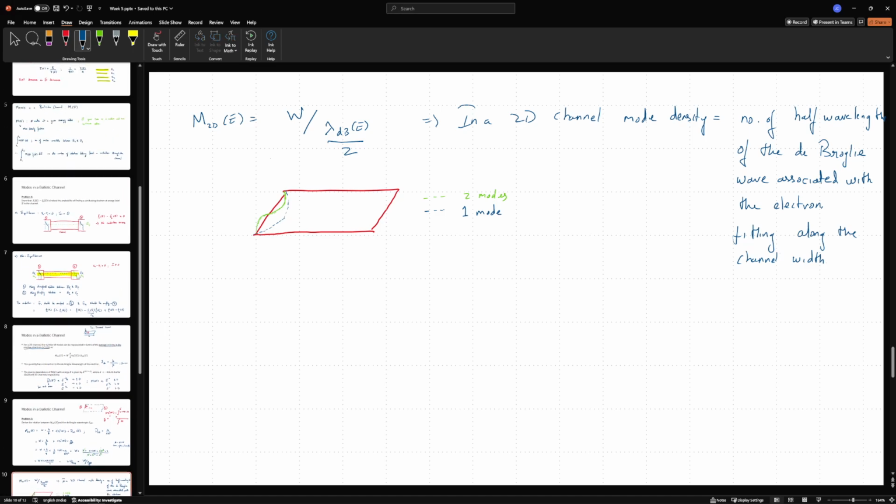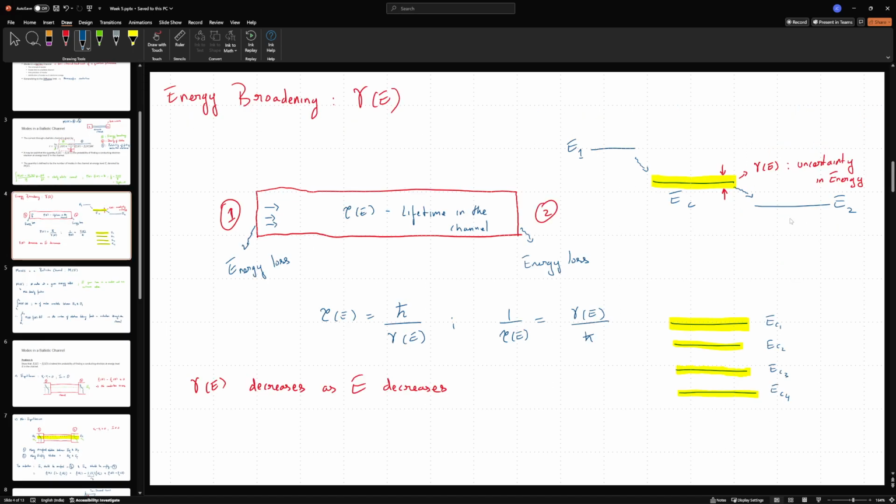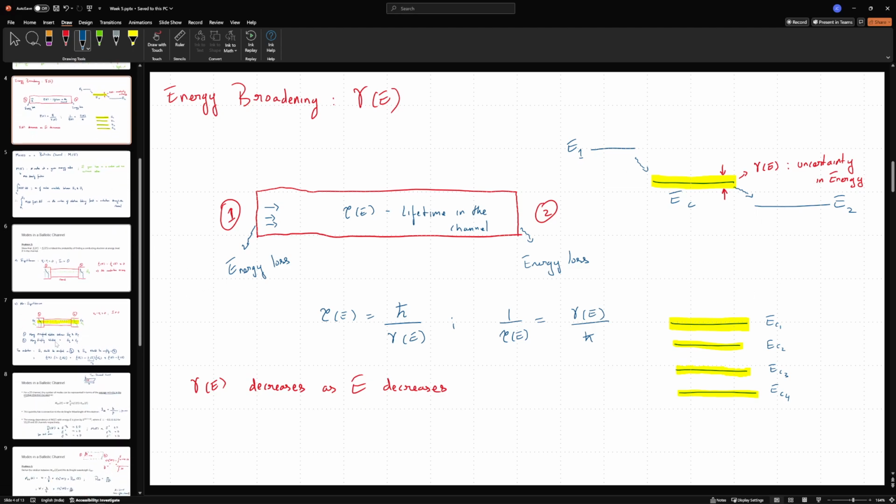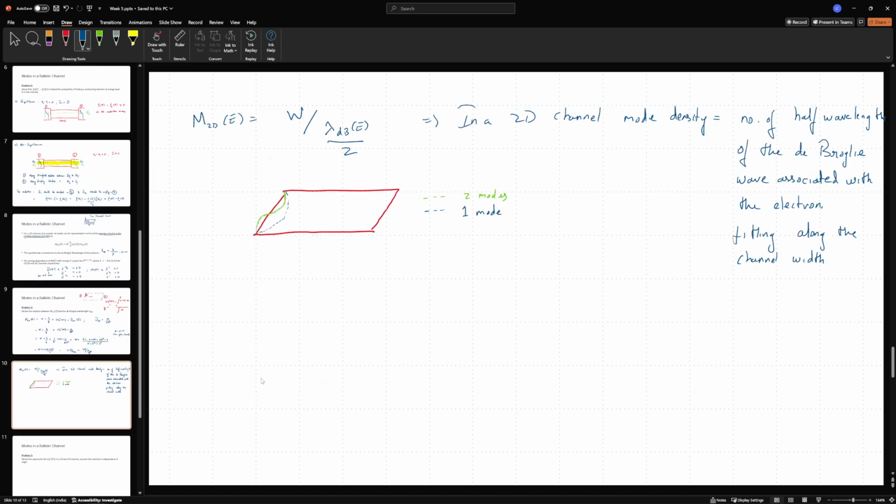Because one could always ask a question like this: since this is a dynamic process, many such electrons can move through the channel, because as they are moving, I can have multiple electrons in the same energy level, at different positions. So all their quantum numbers will not match, and since Pauli's exclusion principle is not violated, I can have multiple electrons flowing through the channel. However, that is not the case. Classically, we will assume that multiple electrons having the same energy can move through the channel. That is why we have the idea of drift velocities and things like that on the macroscopic scale. I shouldn't have said classical. But because of the quantum mechanical nature of conduction here, multiple such electrons cannot pass.